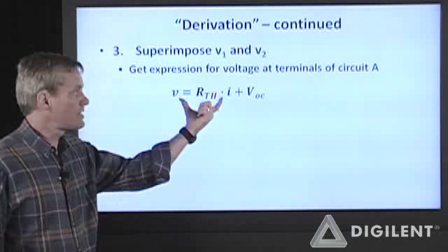This can always be expressed as a circuit where this voltage is now VOC plus RTH times the current I. That's why any linear circuit can be represented as an open circuit voltage plus a Thevenin resistance in series without affecting their terminal voltage current characteristics.